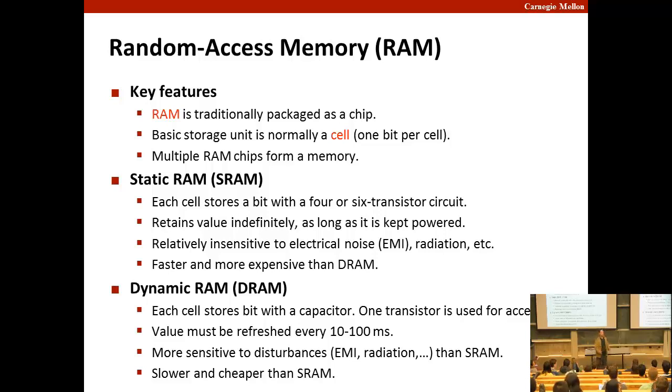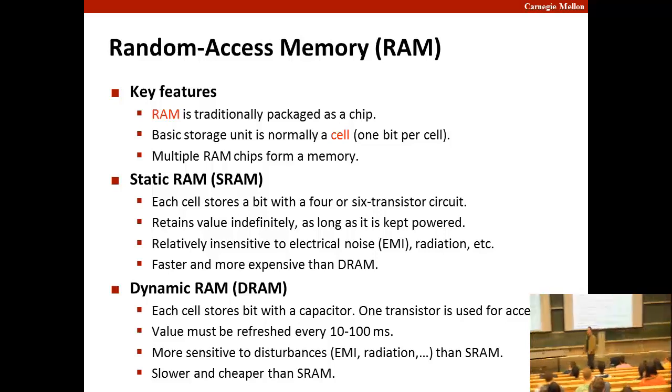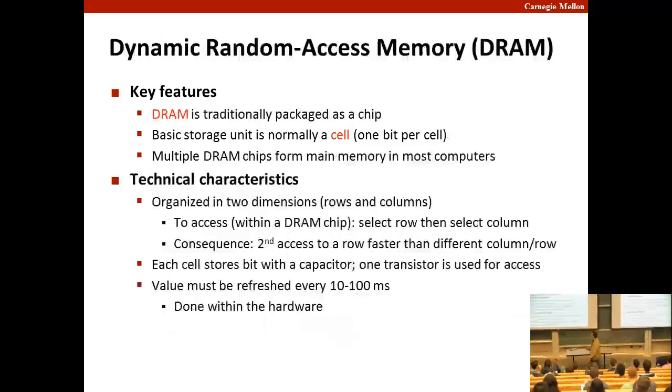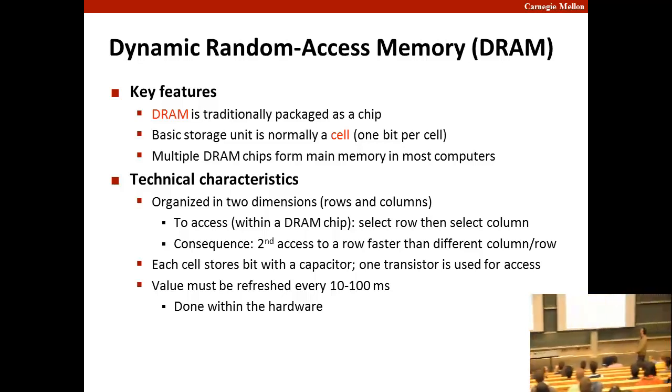That's the more likely place for it to happen. All right. So anyway, DRAM does have this property that requires a refresh. Generally, the circuitry is a little slower. And so what we find if we look at how our memory is organized is that we have small amounts of SRAM used as cache, on the processor itself, off the processor. And then our system's main memory is composed of DRAM. And then underneath that, we have things like SSD or disk as storage, forming our memory hierarchy. And we'll talk a little more about that.